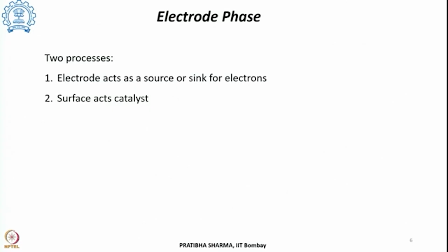Second, the electrode surface acts as a catalyst, and the type as well as rate of reaction depends on interactions between the electrode and electrolyte species. Thus, a rough surface can provide a high and active electrode area to increase the electrocatalytic effect. In water electrolyzers, an electrocatalytic electrode surface is required to promote hydrogen and oxygen evolution at high rate and at low overvoltage.